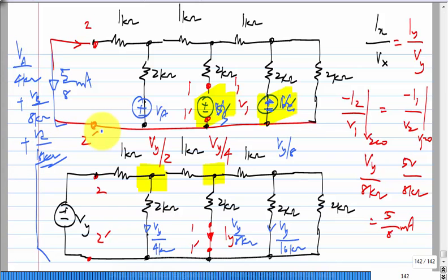This is the context in which it is used most often. There are many cases where you have to find the contribution from many sources. One such thing happens to be, which of course you would not be familiar with now at all, that every resistor has noise. That means that the current in a resistor, if you apply a voltage across it, will be V by R, but because of random thermal motion of electrons, it will have some noise on top of it. There are many analyses where you have thousands of resistors and you have to find the noise contribution from each resistor. And the noise of each resistor is modeled like this.